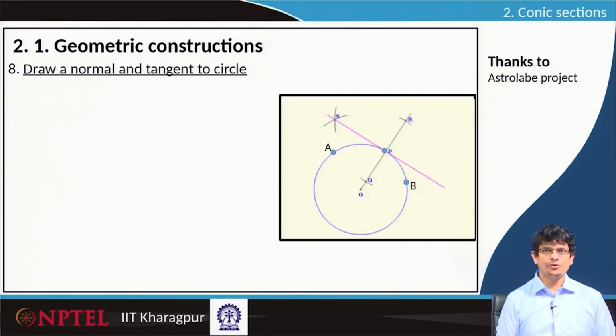The first question we will ask is, if there is a circle, how to draw normal and tangent to that circle from a given point. In certain instances, we might have only 3 points. So, using 3 points, first of all we have to construct a circle, then we will be in a position to identify the center and then the radius. Once the radius is done, we will pick the point, write the normal direction vector, and also be in a position to do the tangent direction. Let us do that step by step.